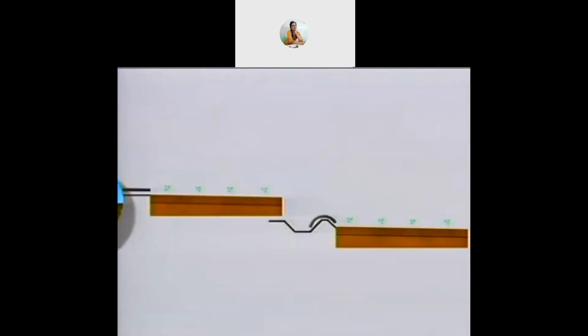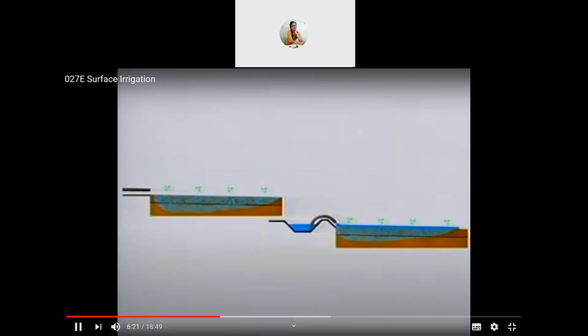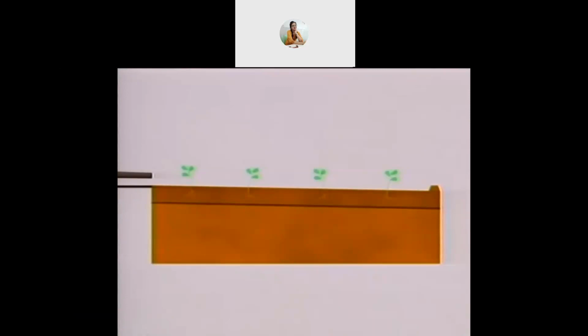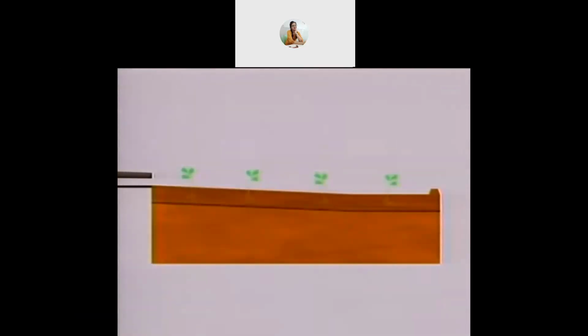Before we look at how to control the flow rate, let's look at some other types of irrigation systems that you might encounter. Some sloping fields have runoff, but the runoff or tailwater is used on other fields or pumped back to be used on the same field. On these fields, your goal is to reduce deep percolation without worrying about runoff. If we block off the end of the field, we eliminate runoff. And if we level the end of the field, we have more area for ponding the runoff water. This is called a modified slope.